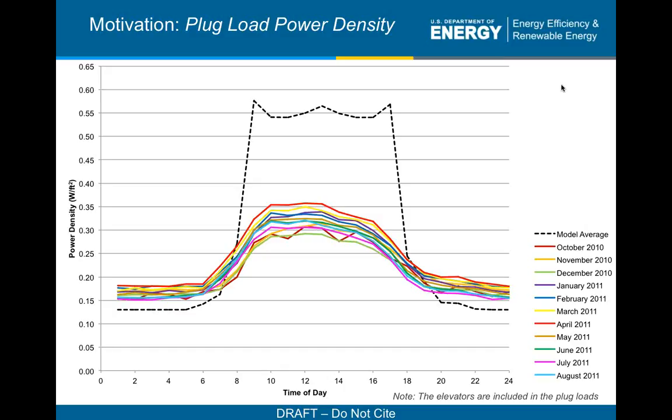However, as you can see, we could still do more at night. So if we choose another advanced power strip or another control type, like a timer control, then we can program our equipment to automatically turn off at night and see even more savings. So even with our net zero energy buildings, we're still seeing savings with advanced power strips, and we could do even more with them as well.